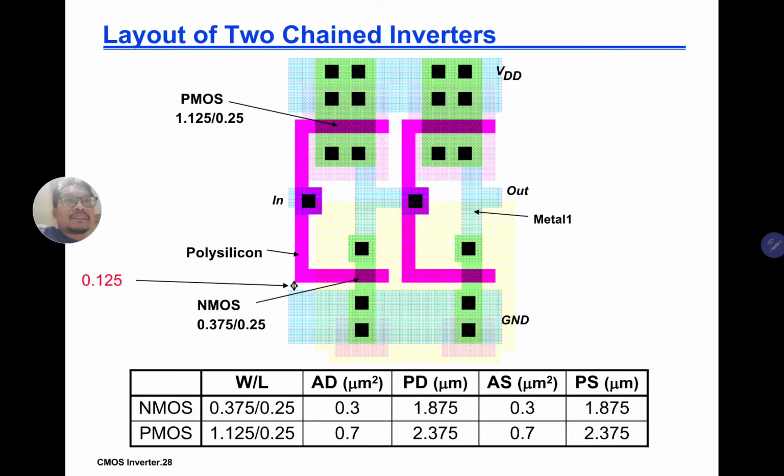So what is the fan out? The C fan out is actually given: C fan out is CG3 plus CG4. CG3 is here, so this is the capacitance there. If you imagine from the top, you have a metal plate, the gate, and your bulk or your channel down below. This is your CG3, and here the smaller one is your CG4.